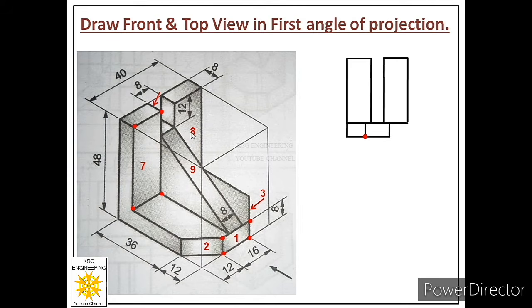If you draw parallel faces first, then it will be easy for you to draw inclined faces. Now for face number 9, these 2 points were on face 1, and these 2 are already located over here because of the drawing of face 7 and face 8. It means now we have to locate these 2 points only. So let us see where we have to locate these points.